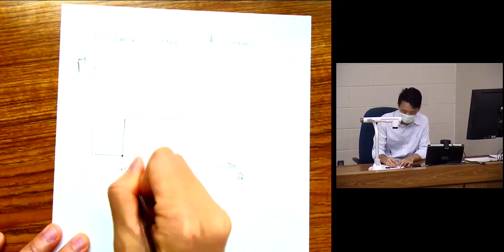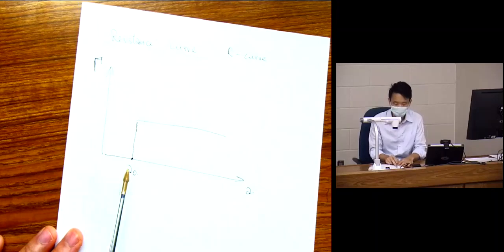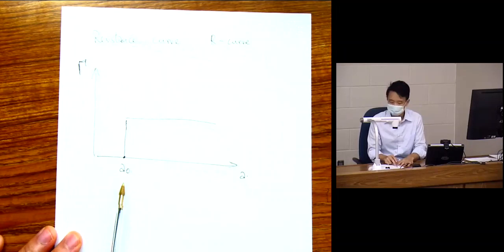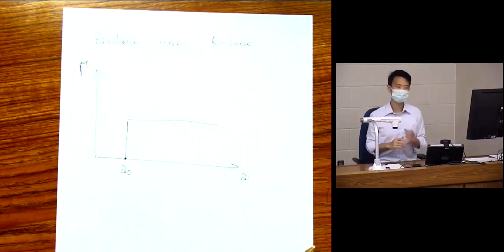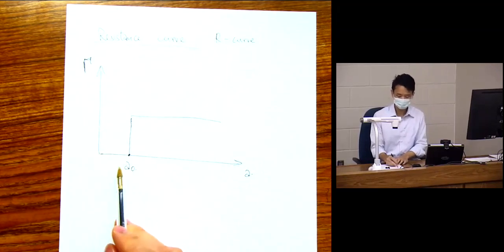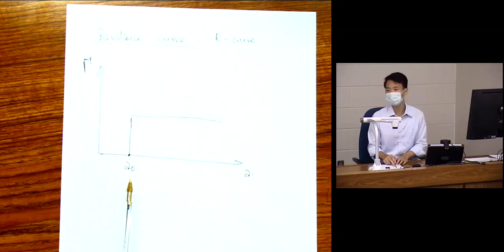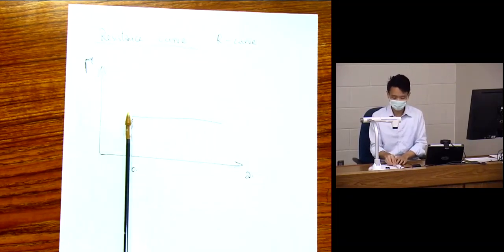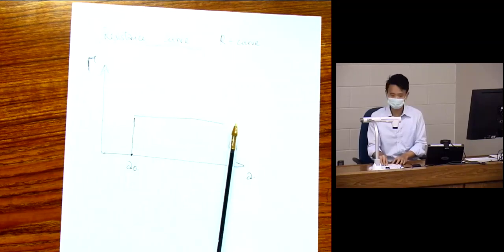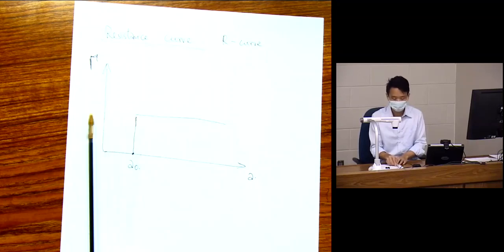Okay, so this is the initial crack length. We have no idea what happens before, because we always start with a pre-existing crack in our material. We don't know anything about the material for crack lengths smaller than the pre-crack length, because we measure fracture energy always with some pre-crack length, right? And this is an experimental value. This sort of is an experimental finding, okay? So anything that you don't measure, you don't show it. So we don't know what happens here.